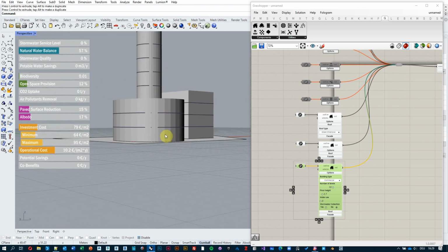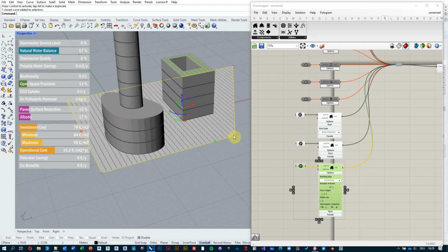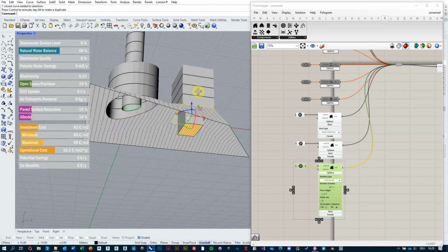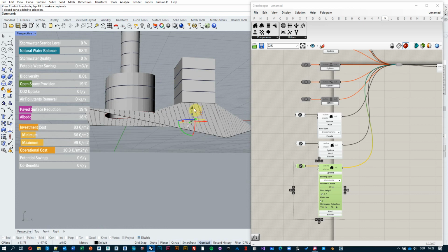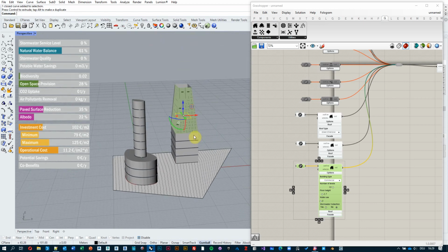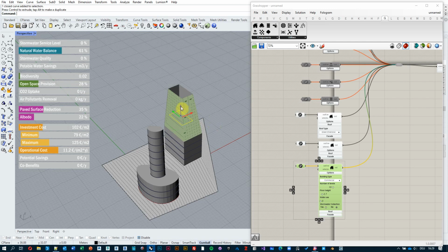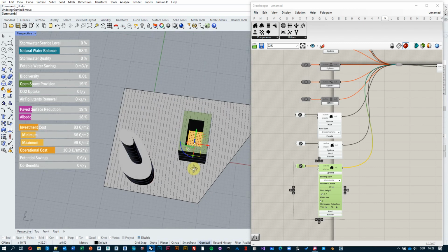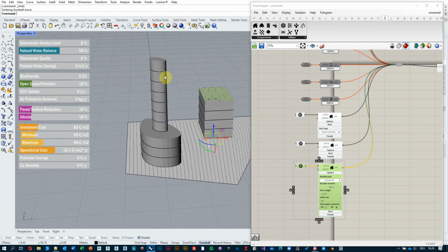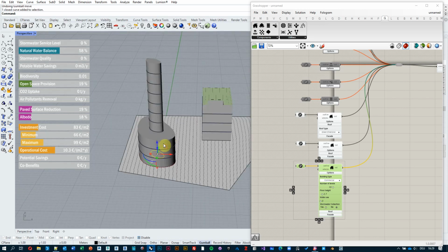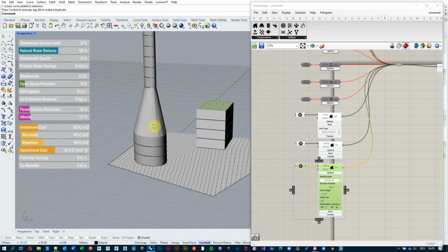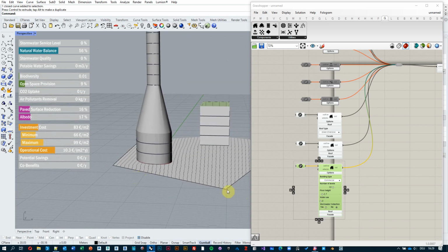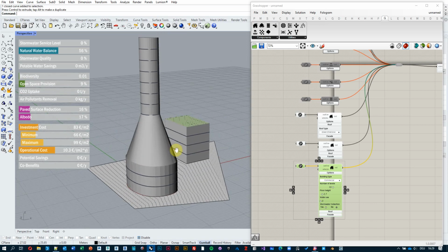What you can do, and this is new in the most recent version, is change them in 3D. You can put them on different levels. You can also do crazy things, which doesn't necessarily make too much sense, but you would be creating buildings that can have cutouts with different 3D elevation. You could move this curve up and create these kinds of buildings. So you can control these curves individually using their control points, and you can also move them at a different Z elevation.